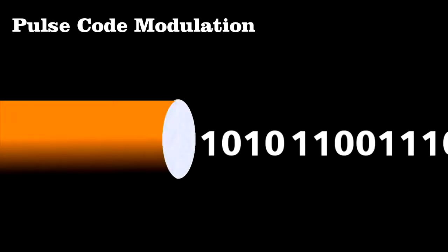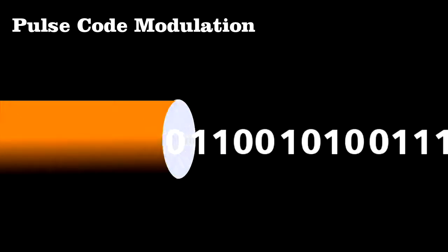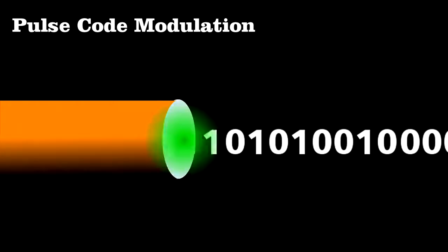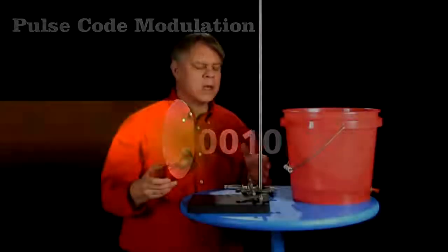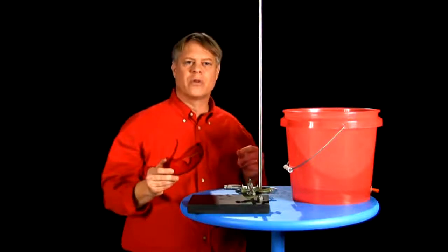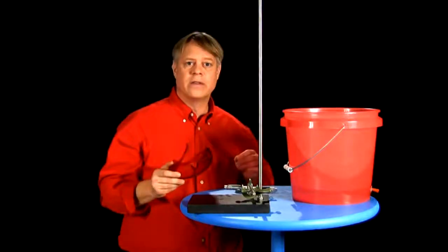And it is that sequence that we send through a fiber optic cable, a flash for a 1 and nothing for a 0. Of course, the exact method of encoding is known at the receiving end, so it is a trivial matter to decipher the message. Now, you may be wondering how a laser pulse can travel nearly 4,000 miles across the ocean. It doesn't without some help because the light will escape from the sides of the fibers.